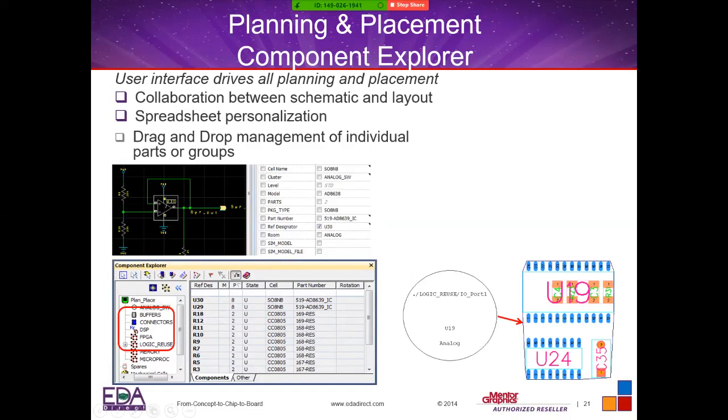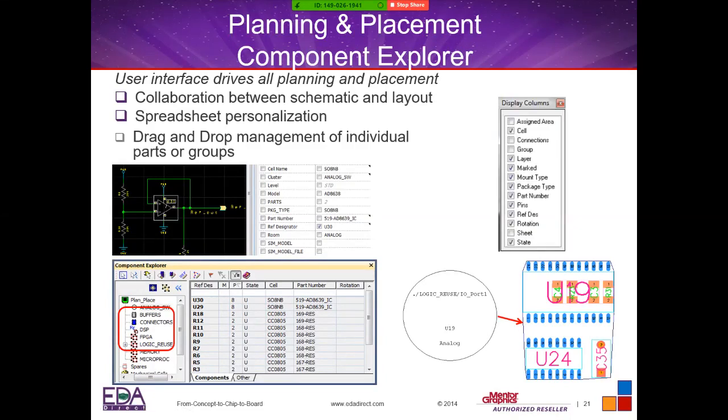So for example, here we have an analog area. We can actually grab the analog area. A circle will appear on the design. All the components from that sheet in the schematic will be inside of that circle, and then you can pull those outside to start doing your placement. So it gives a nice little way to place your components.